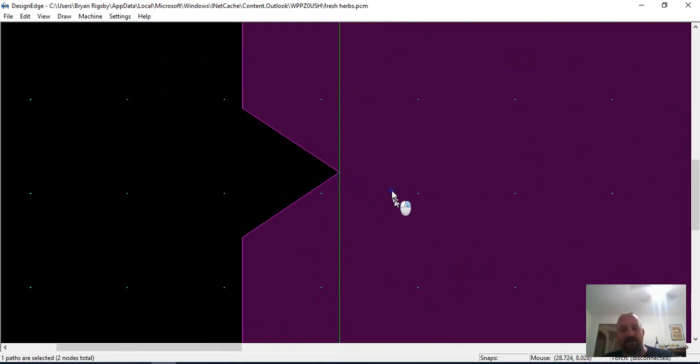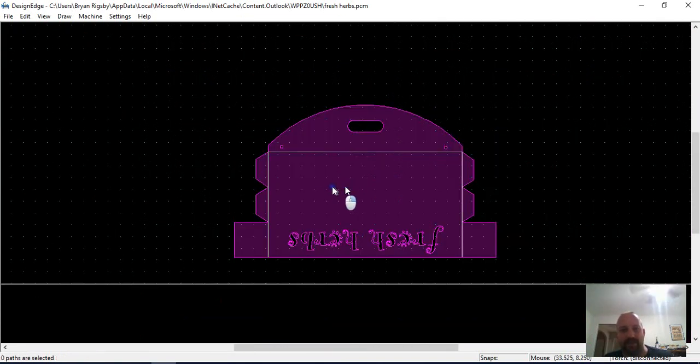I'm going to try something here. You always try to do what's fast, so I'm going to do line, I intersection, and that's going to work because it does intersect that path there to this I intersection over here. And then right click, space bar, I, click near this one, and click near this one. So right click. So now that puts all of our bend lines back in.